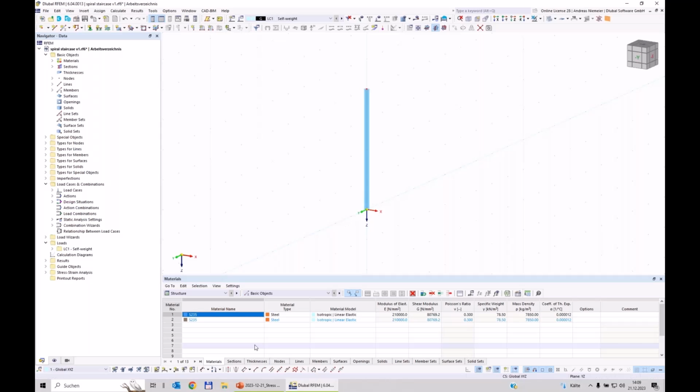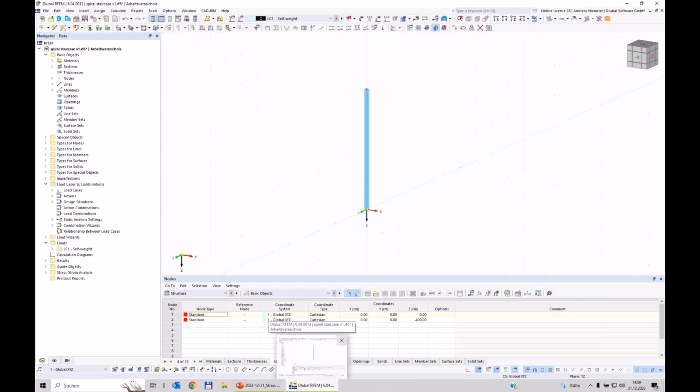have to connect it to my real dimensions according to my technical drawing, which I have here on the desk. So if you have to modify something, you can always use the interaction of the navigator and the table below. So for example, if we have to modify the nodes, you can pick the nodes directly, they will be highlighted, and I can write, okay, this should start 50 centimeters below because the foundation is lower than the first stairway step.